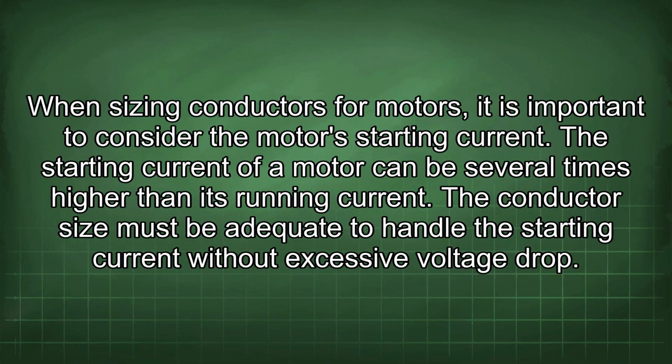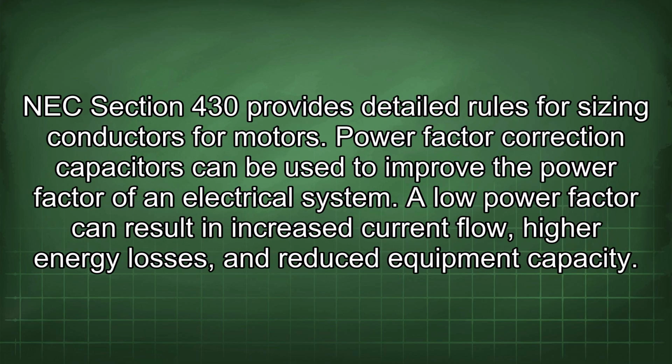When sizing conductors for motors, it is important to consider the motor's starting current. The starting current of a motor can be several times higher than its running current. The conductor size must be adequate to handle the starting current without excessive voltage drop. NEC Section 430 provides detailed rules for sizing conductors for motors.